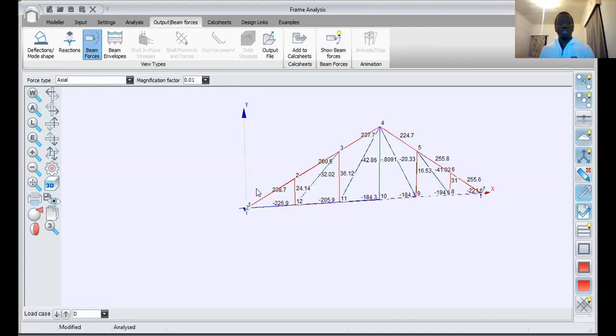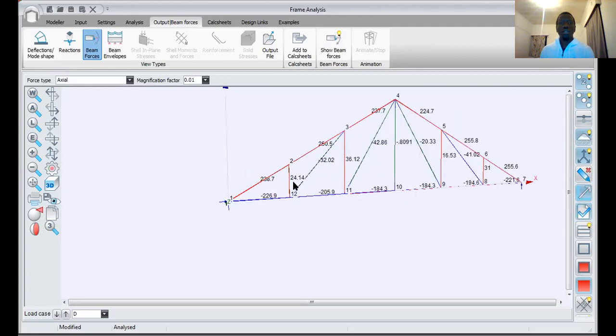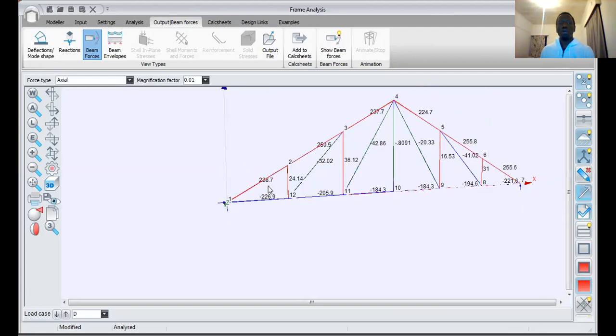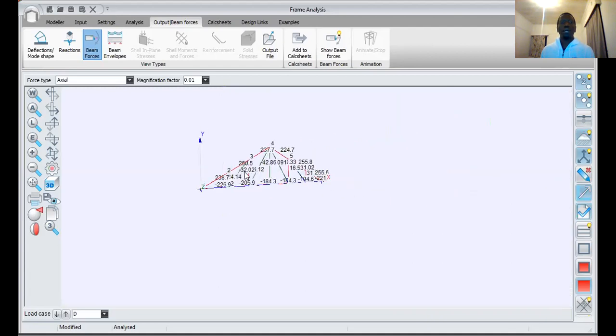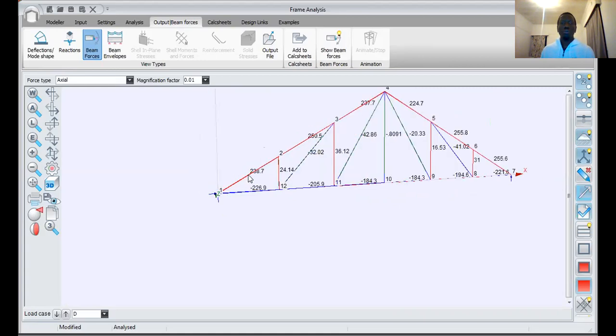You can check the software's nomenclature by using hand calculations, just to confirm whether red means compression and blue means tension. And preferably do that without including self weight, because the calculation including self weight would be tedious.